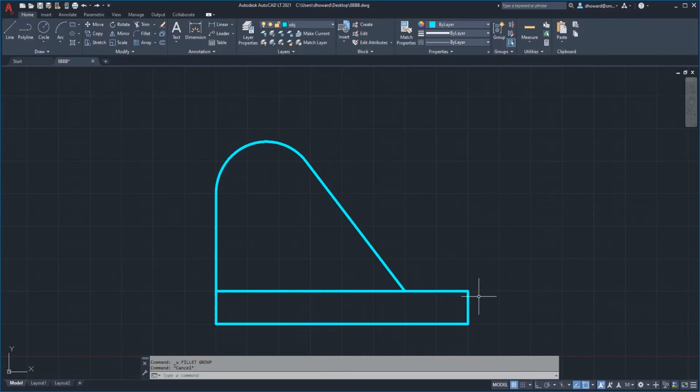So this is kind of a cheat. That last one that we did, I had you guys make that circle. But now you know how to use the fillet command. Check this out. You can use it for anything. I'll click fillet, and again, R, enter, 3, enter. How about this corner? That line and that line.